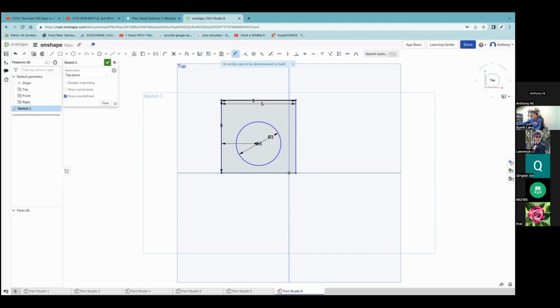Yeah, no. Now just drag it and click on the circle. And now you're dimensioning the sideline. Okay, you see your 2.5 where it says 2.5? Yeah. Just click and drag it away because it's coming in the way. Press escape. Escape. Click it and drag it away. Yeah, so it's not in the way. There you go.